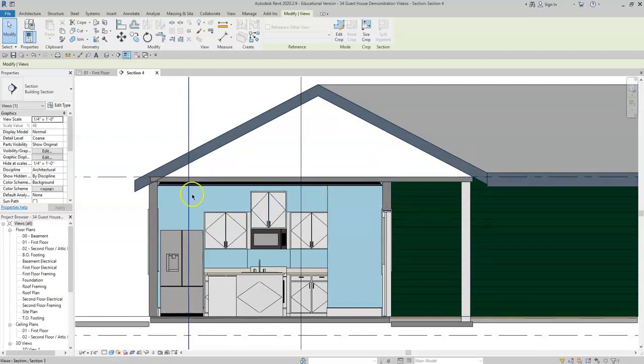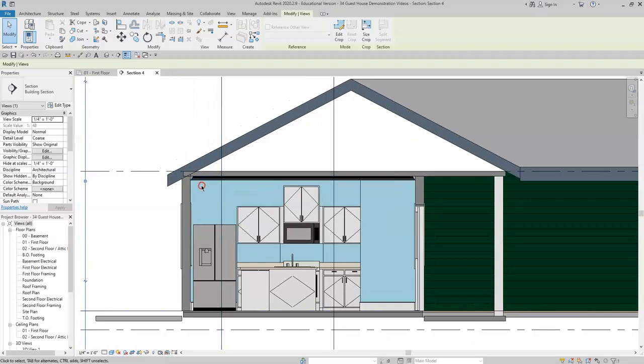We will need to place a ceiling into our home. Now a ceiling is very similar to a floor, except it is the only thing that lights understand to host to. So we will need to have a piece of sheetrock or gypsum wallboard placed on the bottom of our attic floor so that we can host lights onto the ceiling. Right now lights would not host onto a floor, so we need to make this happen.